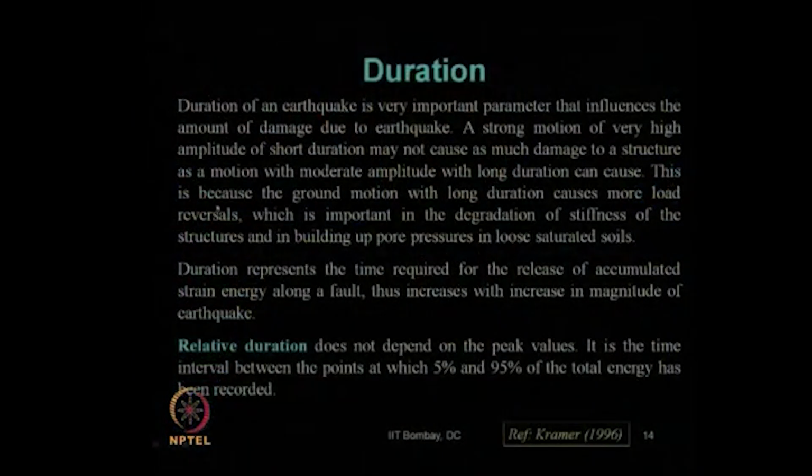This is because the ground motion with long duration, that is, the longer time for which it is lasting, causes more load reversals. That is, once load is applied, then it is taken out. That is the load reversal.